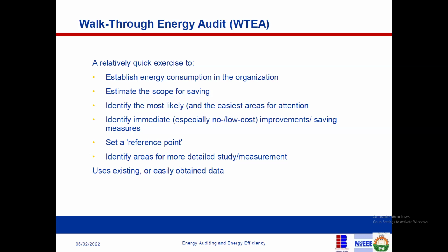Okay, let me take, for instance, a residential house. I walk into your house. So I will check your meter, the consumption. I'll check your energy bills. And I find out that your power consumption is 3 kilowatts. You get me? Remember, this is power. Then if you are getting energy 16 hours a day, I multiply 3 kilowatts by that to get your energy consumption in a day. So let's say your peak power is 3 kilowatts.